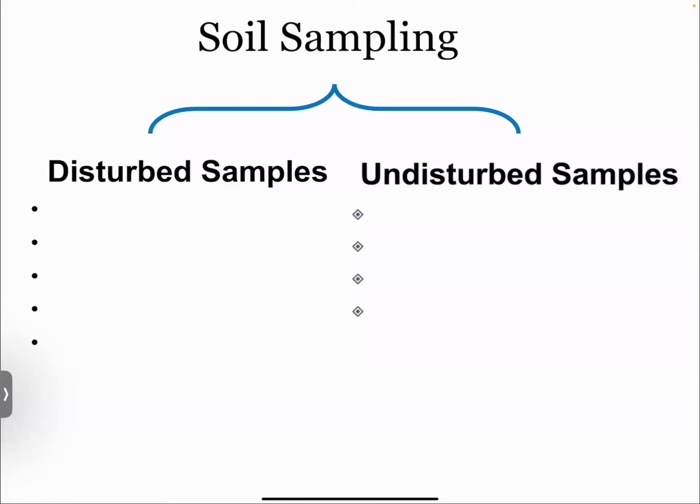And that's why it gets exponentially more expensive with depth, because if you think about it, when we're drilling 200 feet below ground, we are putting 200 foot of rod into the ground and then pulling 200 foot of rod out of the ground, replacing the bit with a sampling bit, and then putting 200 feet back into the ground and then getting the sample.